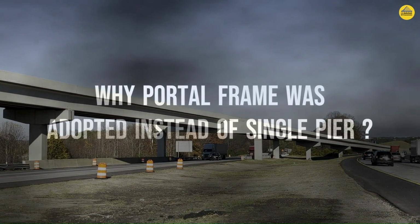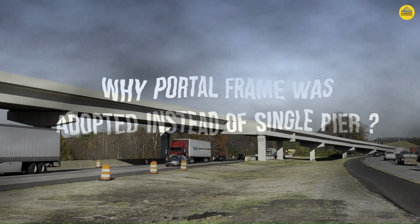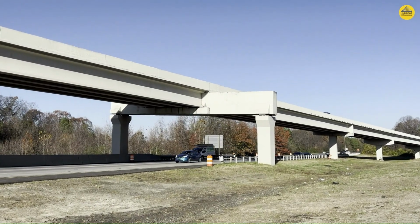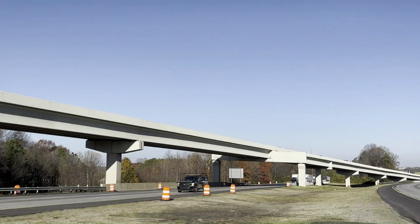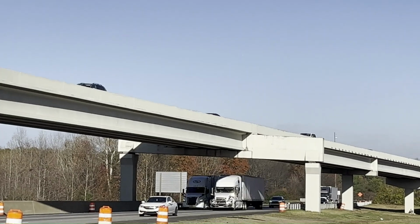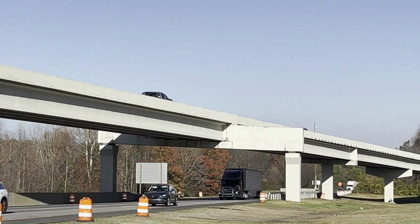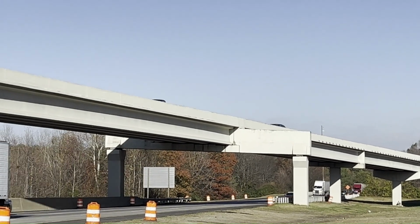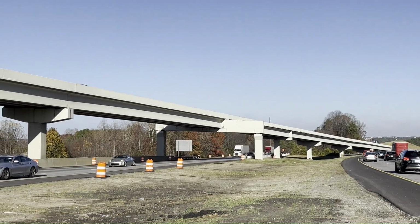adopted at this location when on either side of this portal frame the majority of the supports are single vertical piers with cantilever pier caps. Notice that in the beginning of this episode we discussed that both the alignments at the lower level and at the upper level cross each other at an angle, and both of these roads have a huge traffic volume. So in order to keep a single pier at the location of this portal frame, there are high chances that the pier would have been placed somewhere within the lower carriageway, which would create hindrance to the upcoming traffic, which is definitely not a desirable scenario.